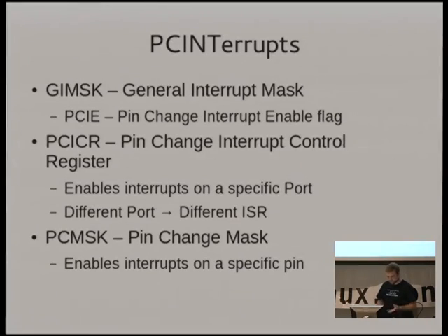So, pin change interrupts. There are a few different registers that you need to worry about to deal with them. You have the general interrupt mask, which says whether it's going to deal with pin change interrupts at all. You have a pin change interrupt control register, which controls which ports interrupts are enabled on. And then you have a pin change mask, which decides which pins interrupts will be triggered for.